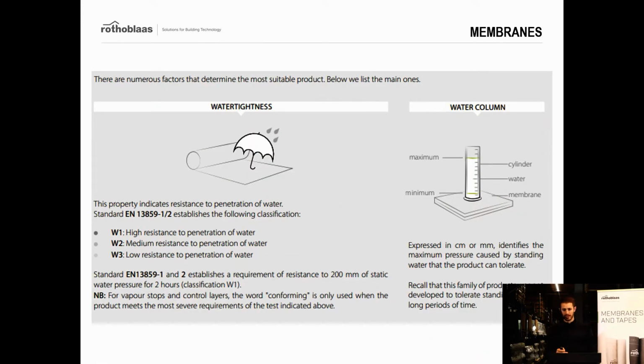Another thing to keep in mind is the water tightness, of course, and I want to spend two words on this. I told you before that all the membranes offer water tightness as a feature, and that's of course a very important feature because we have to protect our building and our structure from the water. But they are not meant to withstand standing water.